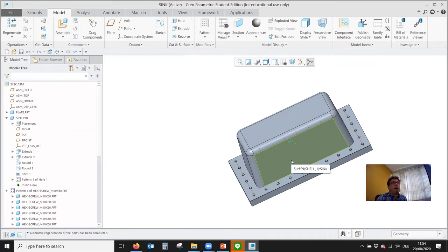So basically we had two major items. Item number one is, if appropriate, use a skeleton model. That is not always necessary, by the way, right? But typically if you have more complex assemblies, it can be useful. So the skeleton basically is like a sketch. It's something you would do on a piece of paper to plan where everything is.